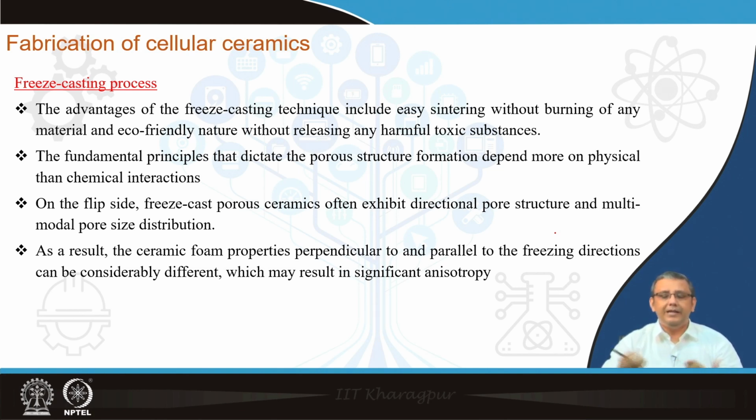In this case, we have only sublimation of water or ice, and that is very environment friendly and less polluting. Also, here we have no chemical reaction; the whole thing is dependent upon the formation of the ice and then its sublimation. That means it's a very simple process, and also the pore size and the pore distribution can be varied over a wide range. Simply by changing the amount of ceramic particles in the initial slurry or by selecting the freezing temperature properly, one can control the pore size and the pore morphology over a wide range, and these pores are all very much interpenetrating.